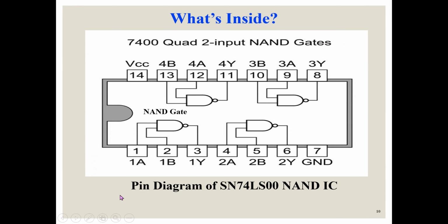This is the 7400 quad 2-input NAND gate. This is a 2-input NAND gate. So now here these inputs have been given. VCC is there, ground terminals are there, and different inputs have been connected here. The pin diagram of this NAND gate is mentioned in this particular slide.